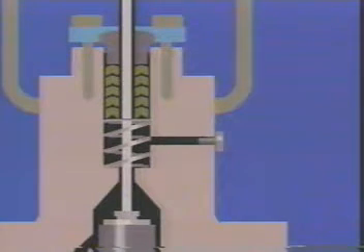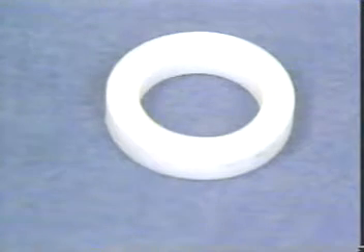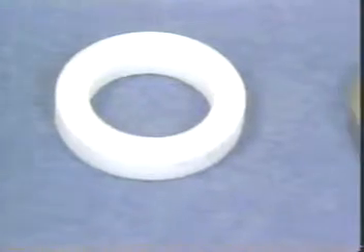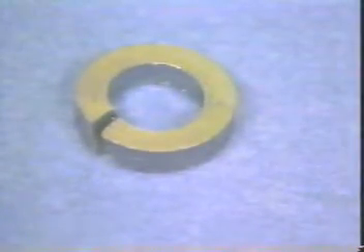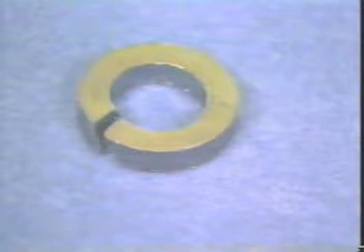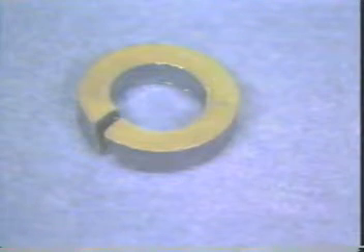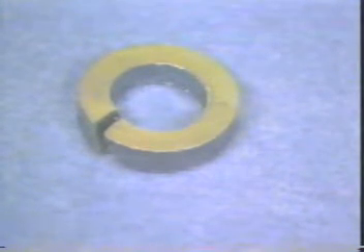Also, keep in mind that the spring is in contact with process fluid and must therefore be compatible with the process. A disadvantage of using Teflon rings as a packing material is that it is a preformed ring. Replacement requires considerable valve disassembly. Other packing materials include rings formed of graphite and graphite compounds, and O-rings and V-rings made of materials such as neoprene. All of these materials may be susceptible to some leakage.